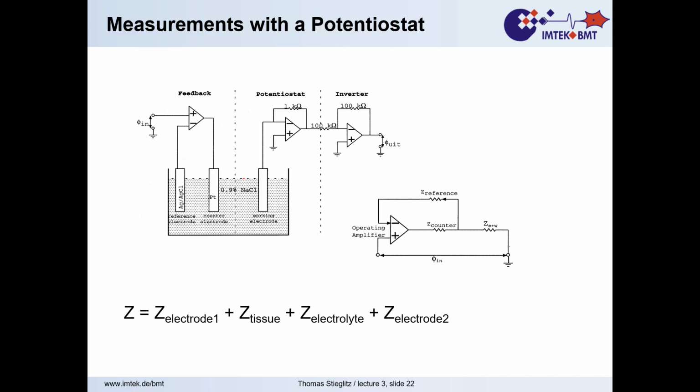And then we have the first operational amplifier where we apply our input voltage. And you see here we have a ground. That's the electrical ground. And this could be, for example, the sine wave for recording the impedance of the electrode. In our case, being simple, this is, for example, a 50 millivolts sine wave.